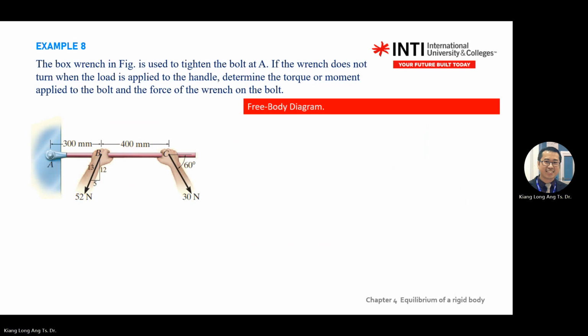This one, just a quick one. This one, example 8, some of you do exercise, you like to do some push-up. So at point A, there's a board there. So board means you fix the object. So reaction force here, you cannot rotate, so there's a moment here, and there's a Fx, Fy for A. Here, pulling 52, given you a ratio 5, 12, 13. So the angle is over here, the theta is over here, so use the theta, then use the ratio.